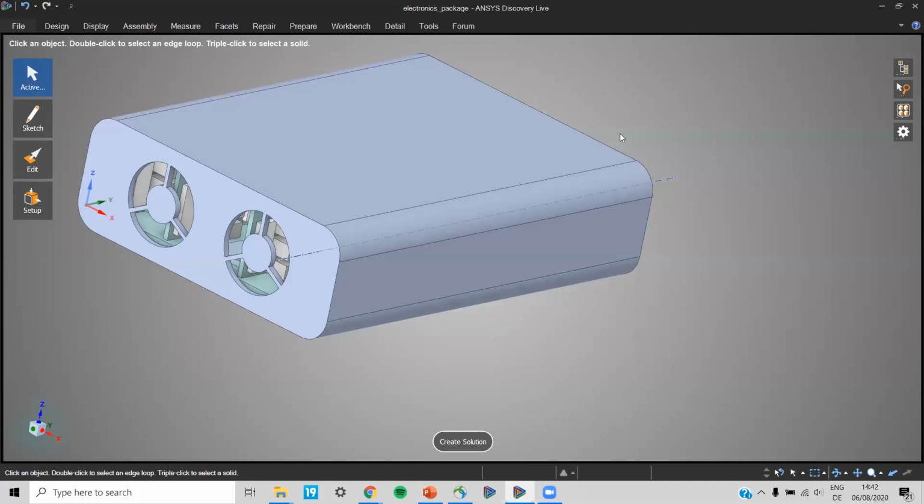Yeah, okay, sir. Thank you for that explanation. The next question: how to smoothen the part after getting the topology optimized? So if I get that question correctly, if you want to smoothen, like you want to improve the part surface quality, there are some repair tools in SpaceClaim, such as removing duplicate surfaces, and improving the STL format of your file. There are these tools in SpaceClaim that you can use. So if I got the question right, then that should be the answer.